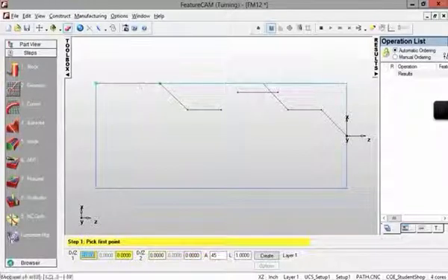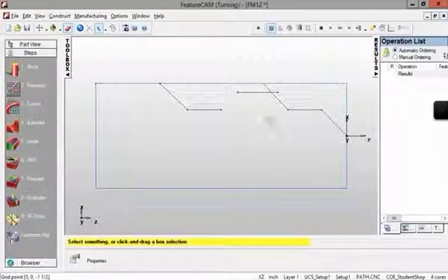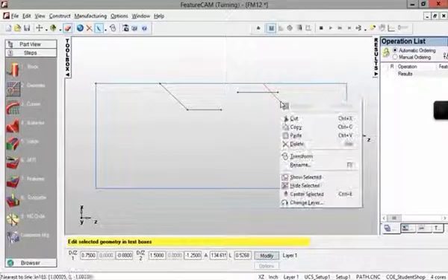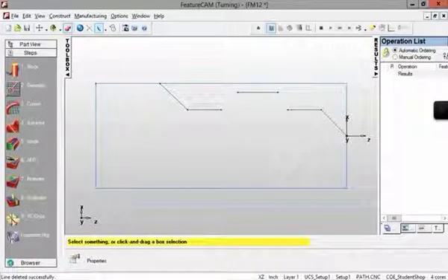As you can see, I made a mistake here. This should be an arc, but for some reason there's a wrong line here. So as we talked about, if you want to delete that, just push the ESC button, and then select this to be yellow or to be red, and then right click, delete. Yeah, it's that simple. So after that, we can draw the arcs.